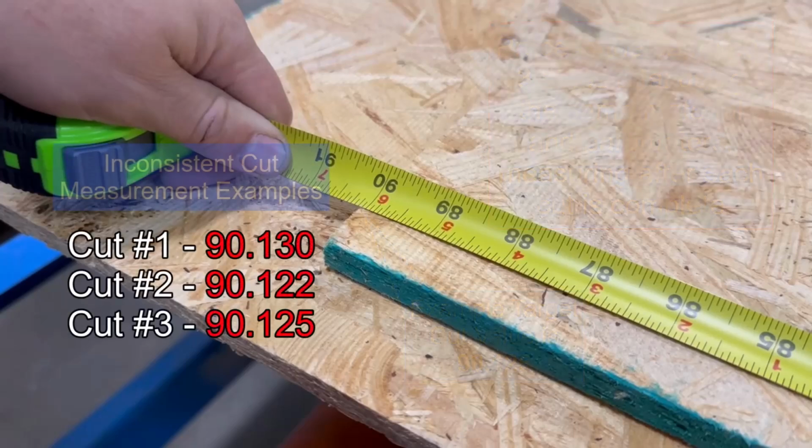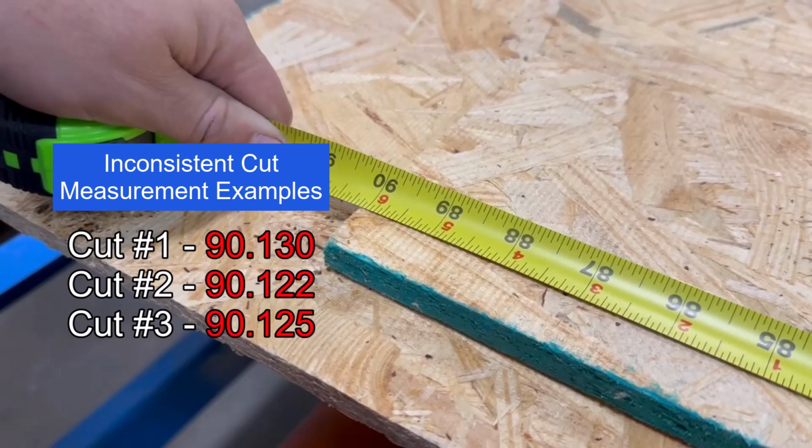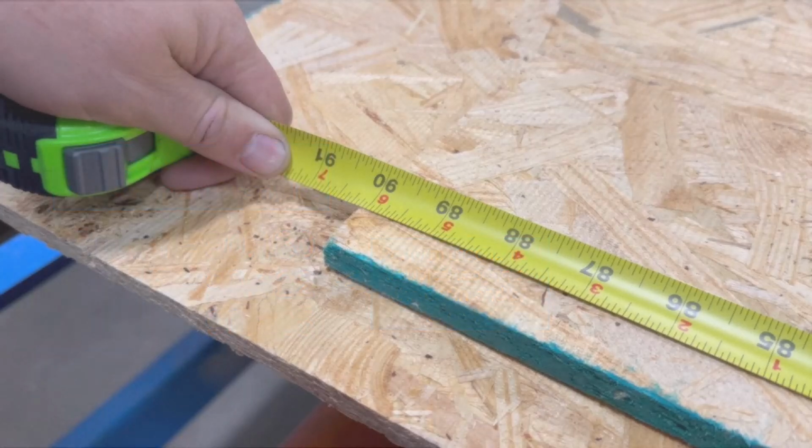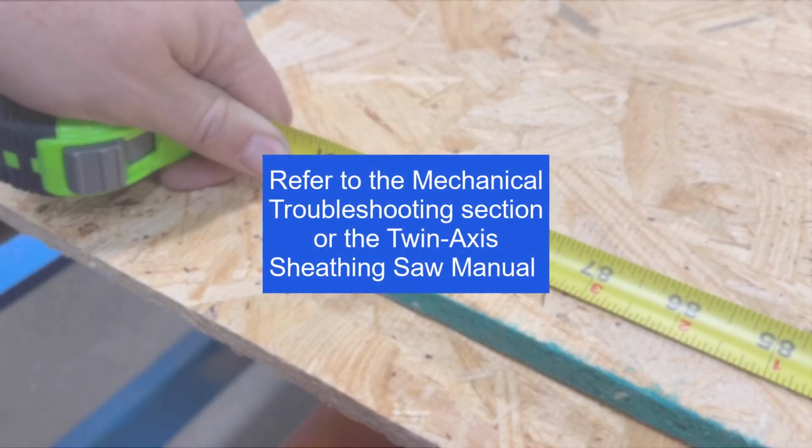Note, if the cuts are inaccurate to what was configured but not identical to one another, there is likely an issue with the encoder, such as slipping, or the chain, such as wear or improper tension. See mechanical troubleshooting from earlier in this procedure for more information.